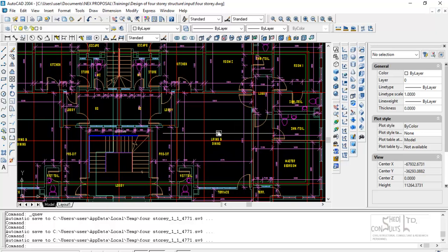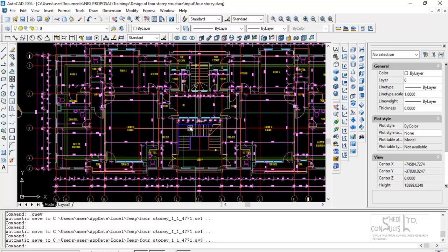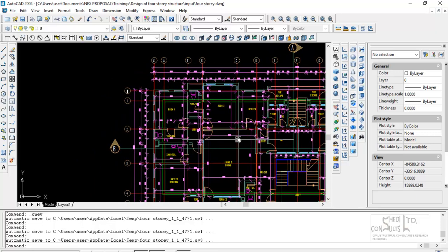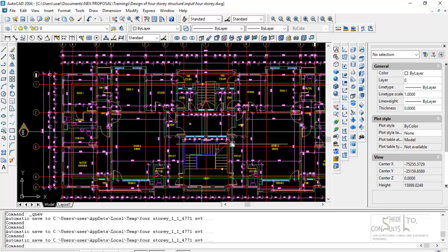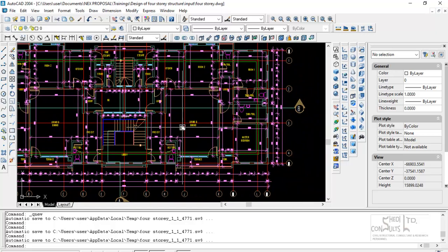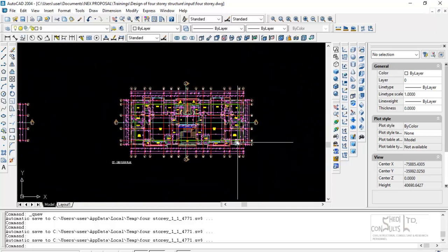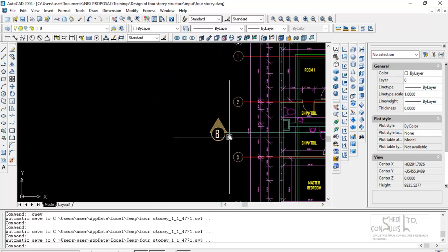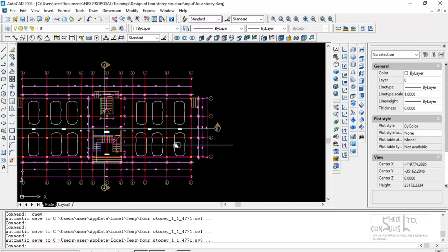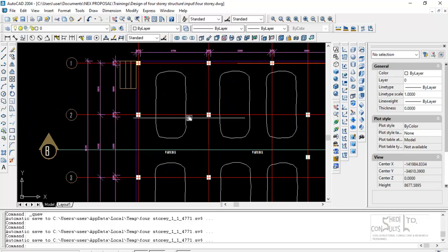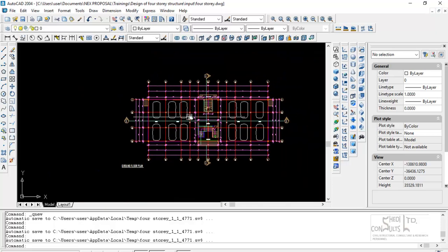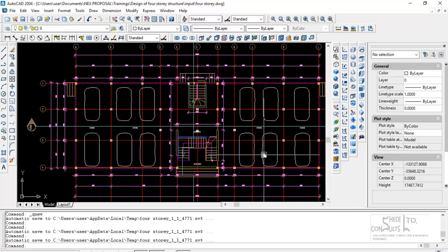In addition, there are sensors placed on the cone tip that measure, in real time, the pore pressure, the dynamic or hydrostatic pore pressure beneath the soil stratum. The cone penetration test can also give you, with empirical expressions, the undrained shear strength of the soil. You can also use it to determine, with the Meyerhof expression, the ultimate bearing capacity of the soil via empirical expressions.